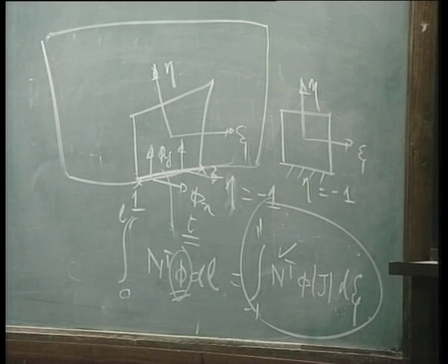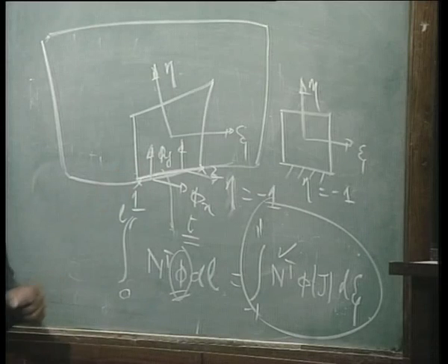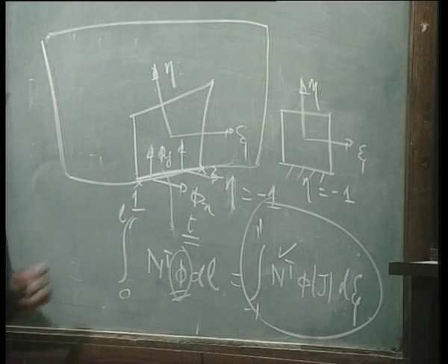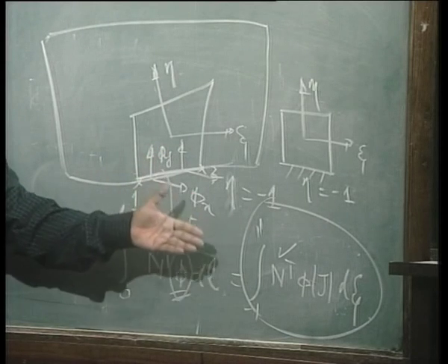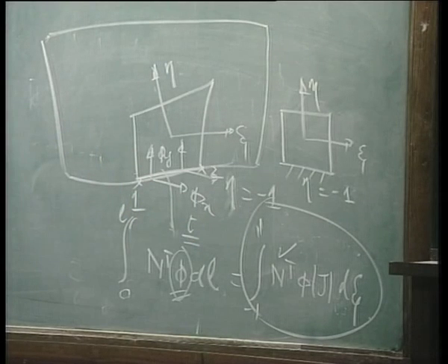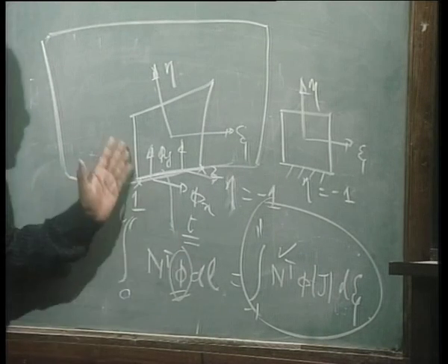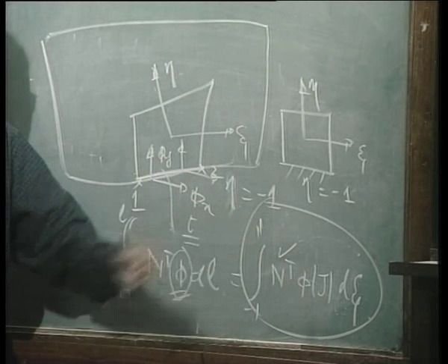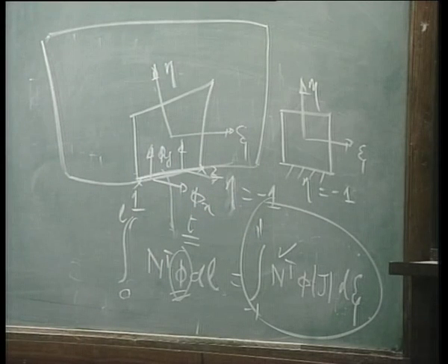There is always a tendency to lump these loads. We will see later in the course that lumping may be very dangerous. It may not be consistent with the result we have got. In fact, these loads which we have calculated by such a rigorous procedure of integration are called consistent nodal forces. They are consistent with our other definitions. So they are called consistent nodal forces.